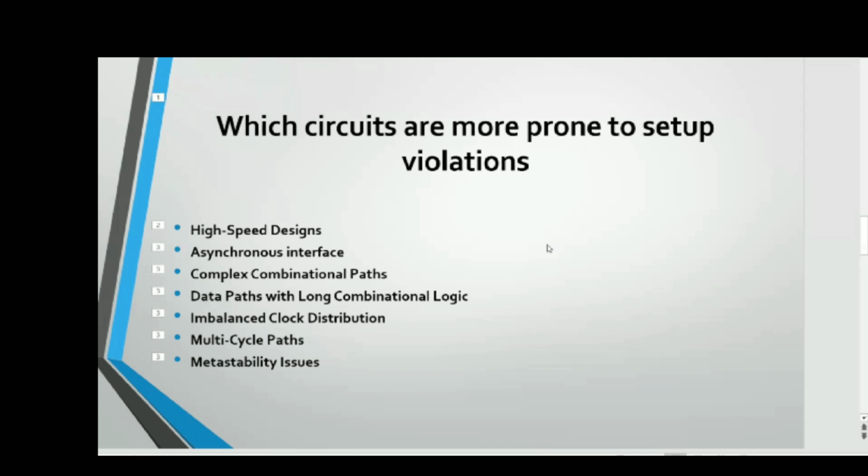And also we have the asynchronous FIFO. These are circuits which come under asynchronous interfaces, which are more prone to setup violations. And also we have circuits like complex combinational logic, where some arithmetic or some kind of operation is going on which is very complex. At that time the data path may take a longer time than expected, and the data may arrive late, and there is a chance of it not becoming stable in the setup window, so we can have setup violations.